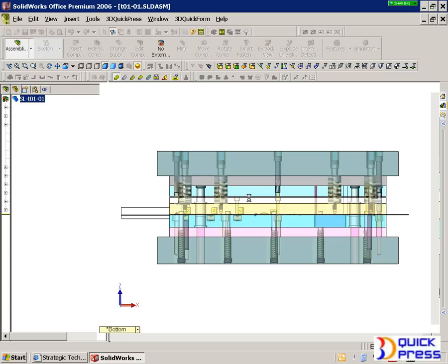Finally, what it's going through now is it's doing the whole creation. You can see it's going through and it's checking, okay, I got a series of punches, they have to go through certain plates, and then of course we got that insert sitting on a punch, so that means that the insert needs an opening, and the punch itself has to go through the insert. And all these things have to be figured out. So we're doing it very, very quickly and much simpler than you doing it manually, because we won't forget about a hole or two. You might be able to do that. We want to take that off your mind, and we want to allow you to do true value work, not just redundant simple operations.